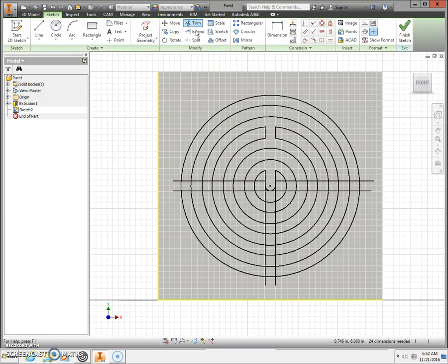Next, we're going to take care of the right hand side. Let's trim out this line that's coming from the right. This is the groove, so my BB's in the middle. It can come out to the outer right hand side. I'm going to cut through this second wall that's here. I'm going to skip this third wall and cut through the outside wall here and trim away the tags on the side. Let's do the same thing to the left hand side.